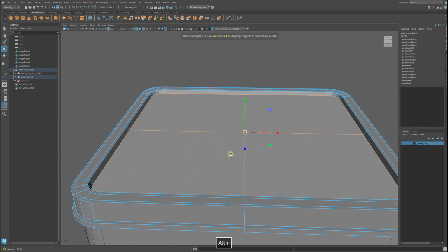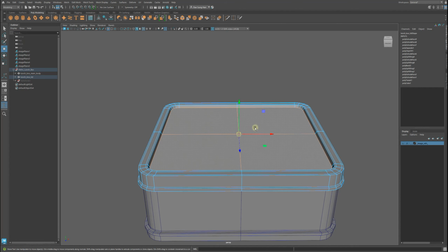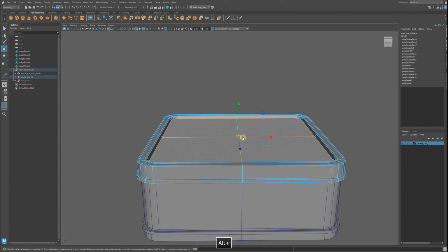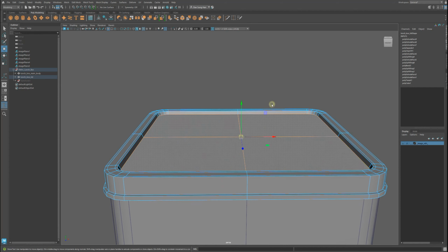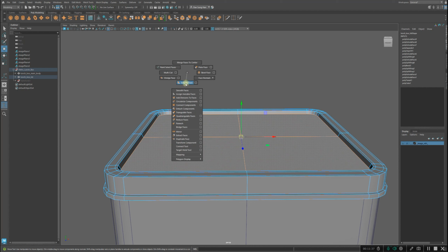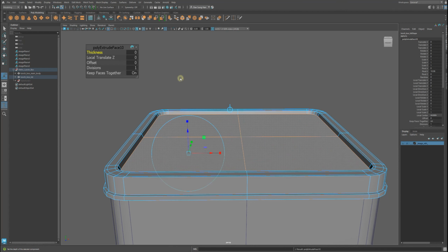From there, press W, and I'm going to do another extrude. Because if you try to just press that, it's nothing. That's why I'm going to do another extrude. It's another function altogether. So shift right click, extrude face, right? I'm going to use my offset, right, to 0.1, 0.5, 0.3, 0.2, maybe 0.3.